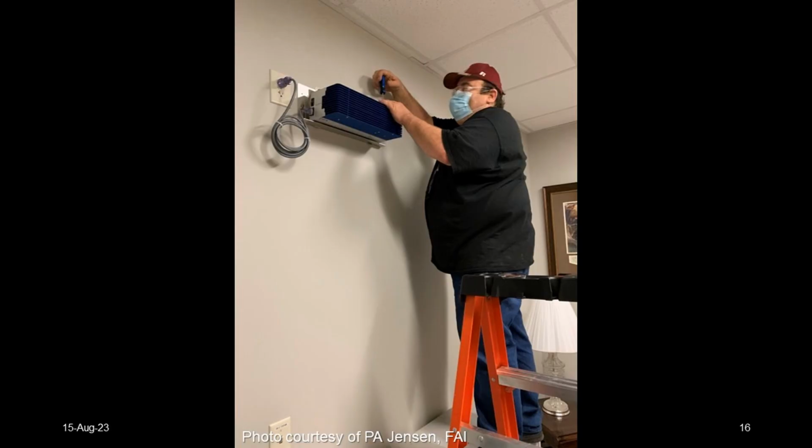So here's somebody, he's got his safety glasses on. This was during the beginning of COVID, and he's opening up the fixture. This outlet is on a switch, so he turned off the switch and put painter's tape over top of it and marked it "leave off." It's not quite the official OSHA lockout tagout, but it's good enough. And ideally, he could have just unplugged it as a second safety feature, and then that way if somebody did play with this switch, it would not perhaps expose him.